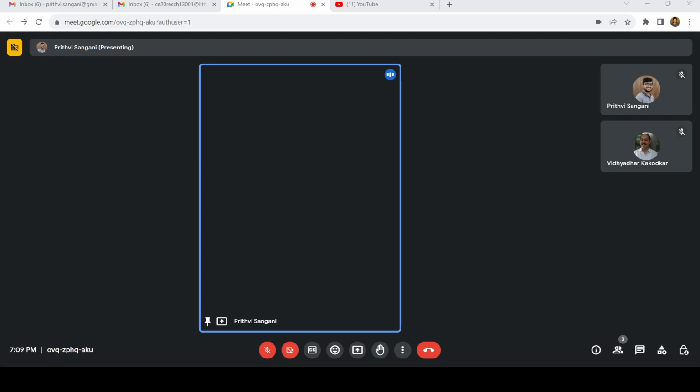So what is the net force there? 52.3 minus 20. So that will be 32.3. So this is going to be 32.3. So what about the vertical force? Like I said, this is a junction, right? So you have only vertical force acting of 34.6. So there should be tension 34.6.